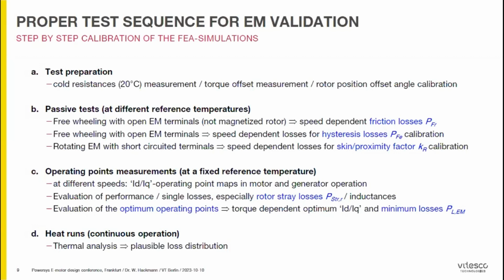And with such a set of measurements, we can then evaluate the maximum performance, the single losses, especially also the stray losses in the rotor, and the inductances. And out of this set of measurements, we can use it for the calibration, for the tuning of the motor control software, because out of this we are getting the optimum operating points, so the max torque dependent on current.